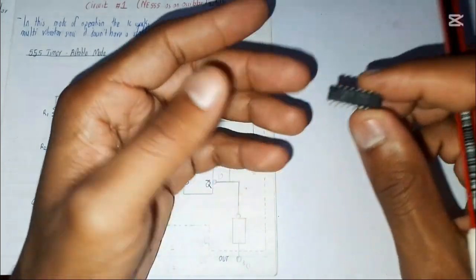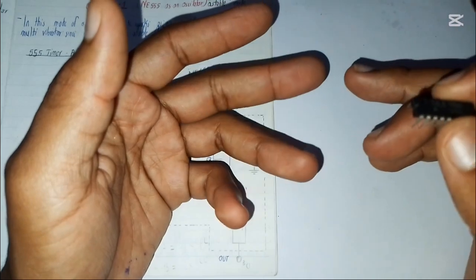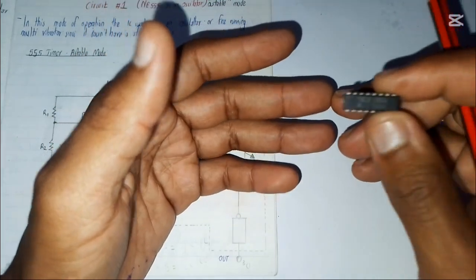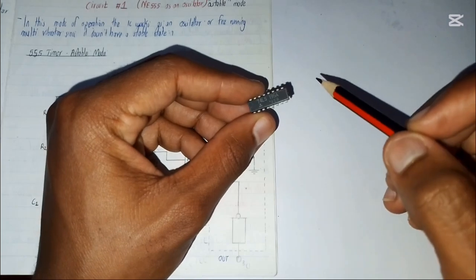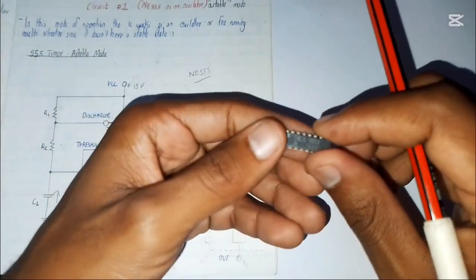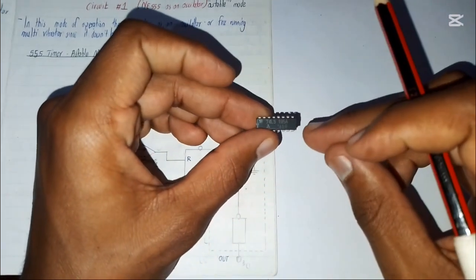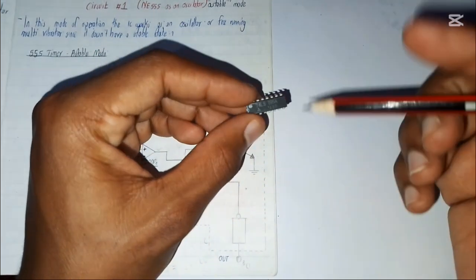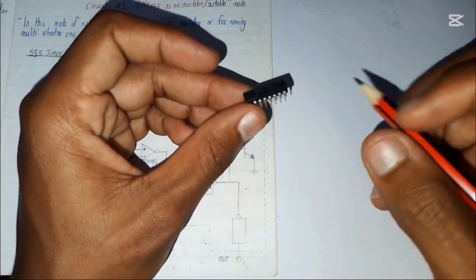I did a serial input, serial output, parallel input, parallel output, serial input, parallel output, and the last configuration was a parallel input, serial output, which after many attempts, I didn't succeed on making using this IC. It's quite hard to configure or manipulate this IC to give you a parallel input, serial output.